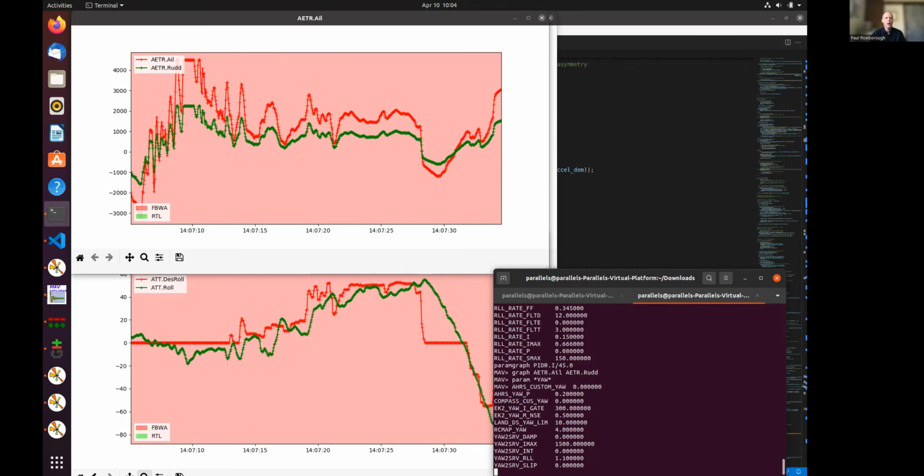Anyway, it's a bit hard to do an inspection of the airframe now, and I think there's not much to be gained other than what we can glean from the log. But it was interesting to see how the side slip came in and really fought the aileron, and how that integrator wound up. If you run an auto tune, the Believer really does fly very nicely. Oh yes, they do. But you need to have done that auto tune on it.